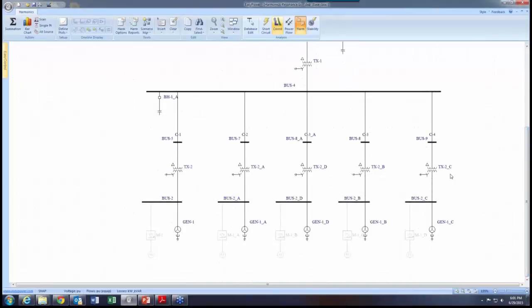Once the dimension and size of the system goes up and the number of equipment adds up, then it becomes more complicated. You perhaps won't be able to use that formula as easily as I did now, and you would rely more on software packages, obviously, like EasyPower, where the harmonic module, the harmonic focus is really strong. It's very well written, prepared, and covers almost every need that you might have for your study. So that being said, okay, let's take a look at the 7%, see where that 7% comes from.